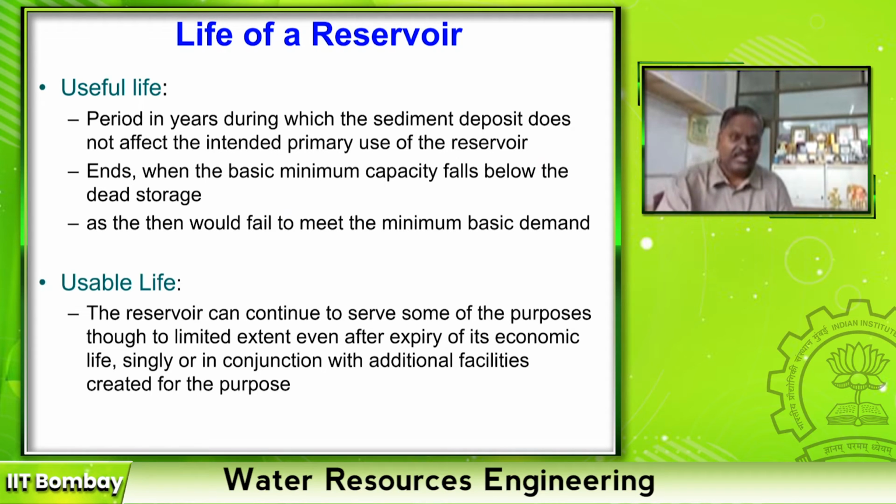So what is hydrological life? We can divide that into different lives. That means whether the stored water can be economically usable. That is why people call it useful life. Useful life is nothing but the period in years during which the sediment deposit does not affect the intended primary use of the reservoir.